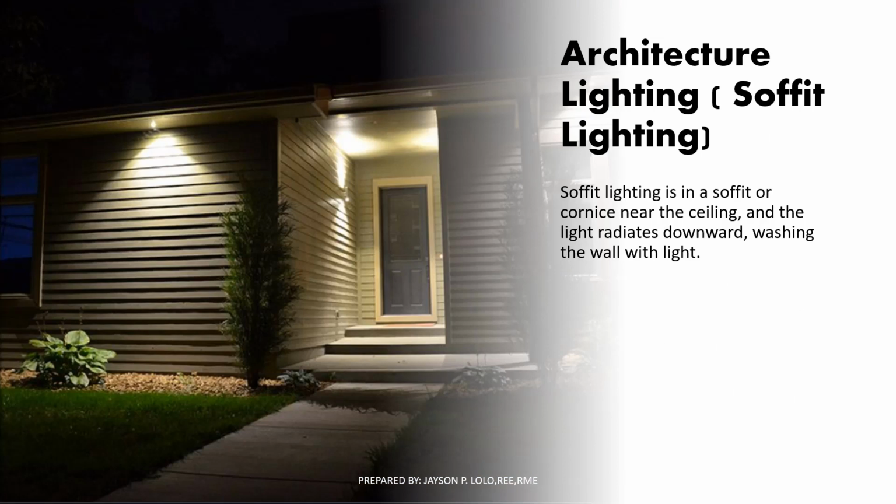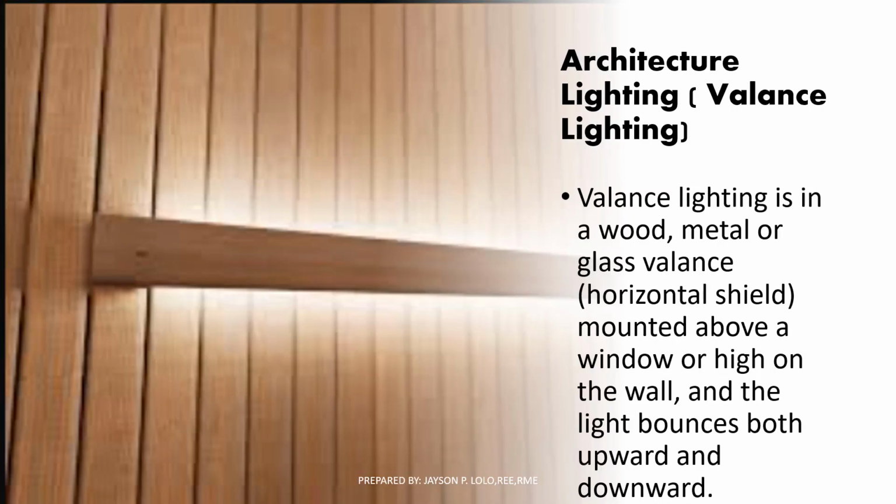They are applying the soffit lighting, where it is corniced near the ceiling and the light radiates downward, washing the wall with the light. The third one is commonly applied on wood, metal, or glass valance. The application is that the light will bounce both upward and downward. This is the valance lighting.